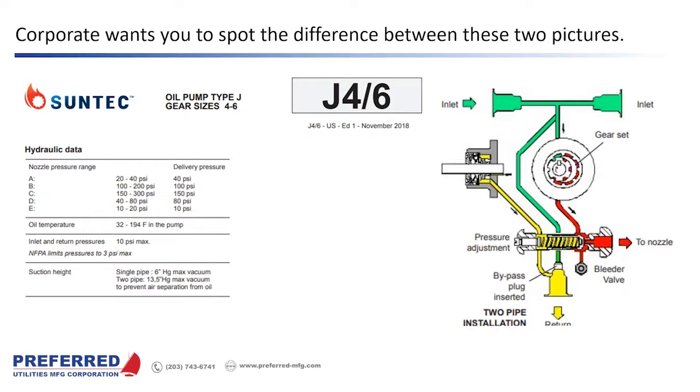Although as soon as I said that, I realized we just helped design a job in Chicago where it was like 400 feet between the main tanks and the boiler room. And we did put a day tank in the boiler room with transfer pumps to power the boiler loop, and transfer pumps to get the main fuel from the main tank to the day tank. But we did that because there was a huge distance between the main tank and the boiler room. That's the only exception I can think of. Otherwise, do not use the day tanks with boilers.